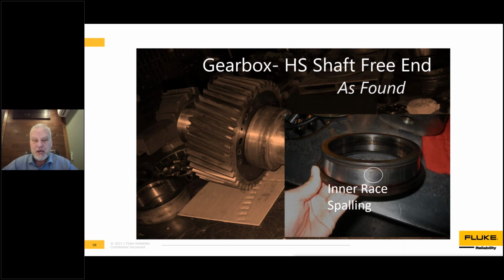I don't think it's much better. I would say that the results are roughly equivalent. So it depends on the ultrasound that you're using and how you get your results. Again, it's two different approaches, but both of them use this high frequency data approach. One of them is using contact spectral analysis in the same instrument that you're doing vibration analysis in. But I won't discourage people from using ultrasound because it potentially can get very similar and parallel results.